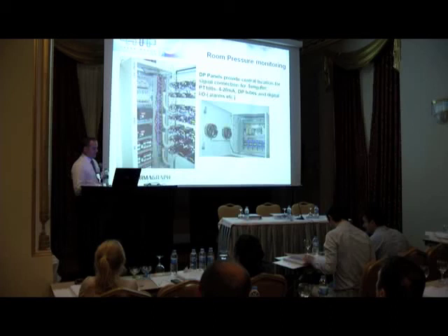We also have a standard historical report, which is a log every 30 seconds or a minute of every value that comes into the system. It just logs it. Personally, I think the best thing it does is at the bottom here, it gives you a summary. So it tells you the number of samples taken, and the mean, maximum, and median values for any values. So if you select it over the day, you know your maximum temperature and minimum temperature that day, just in a simple 2-line summary. And you can choose to hide this raw data, so you get this simple summary at the bottom.